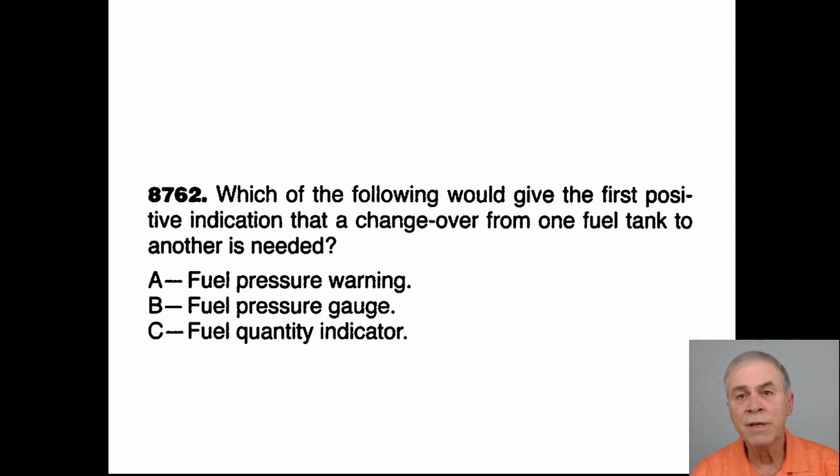Which of the following would give the first positive indication that a changeover from one fuel tank to another is needed? All right, now we're hammering on the same question, same answer. This time we do have two options that say fuel pressure, so let's explore the difference. And this is the first indication that you have to change tanks, not necessarily the fuel quantity indicator, which isn't a positive indication.